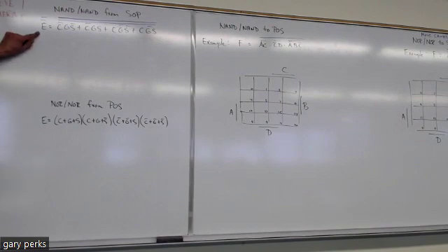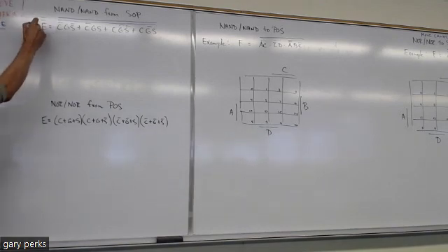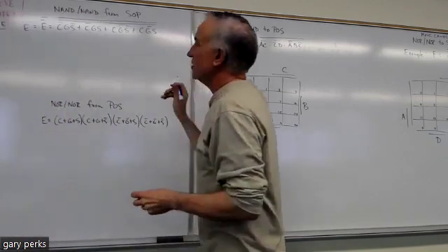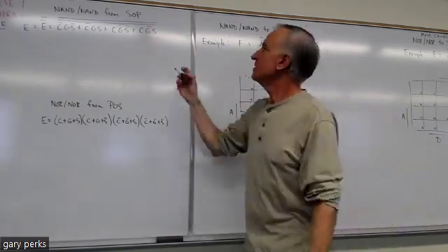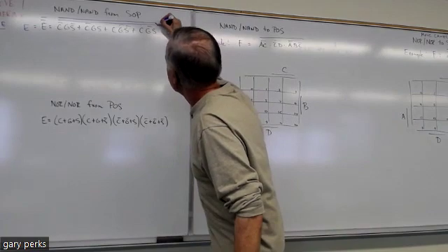What do you think? If I take a variable and I double NOT it, what do you think that's equal to? Just the original, because it's like passing that through two inverters. It's like taking E, putting it through an inverter, making it not E, and then putting it through another inverter, making it back to E. So the double NOT of a variable like this is just equal to the variable. Now, we're going to do this because we want to get NAND, NAND.